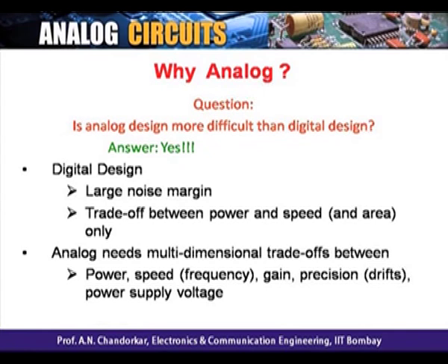So what is my answer to you? Is analog design therefore more difficult than digital design? My experience of 29 years says yes. Because digital design has a large noise margin, and you can have three-way trade-offs only: power, speed and maybe area. Whereas analog needs multi-dimensional trade-offs: power, frequency, gain, precision, power supply and many more.